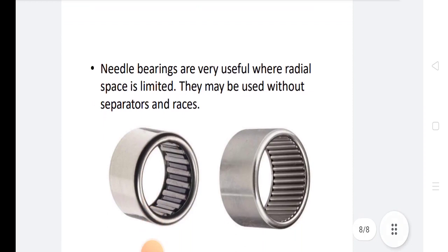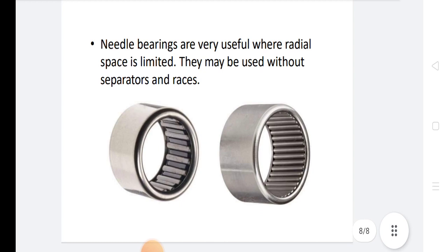Also, for machines in continuous use of 20 hours per day, the life is 40,000 to 60,000. Machines required to work with a high degree of reliability 24 hours per day, life is 1 lakh to 2 lakh hours. So this is the life of bearing.